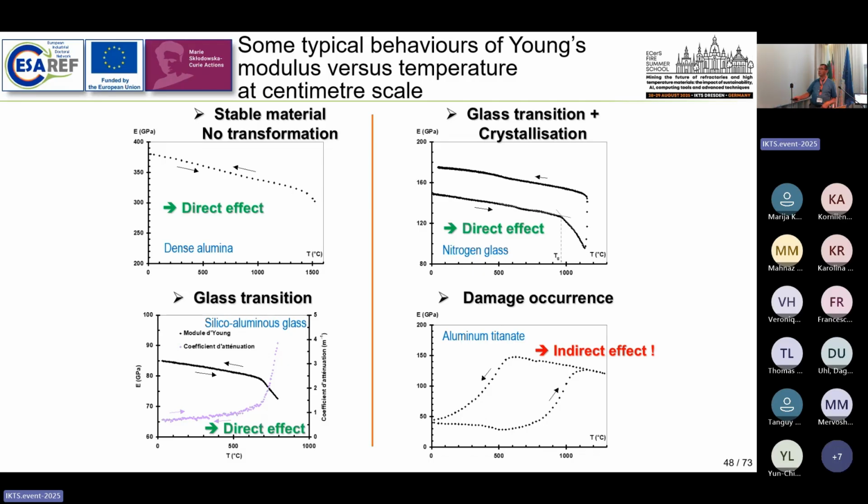Just crack evolution, you have a perfect signature of a hysteresis curve, which is a typical signature of a material containing cracks. Of course, for conventional mechanics, cracks are usually bad and decrease the property, but for refractory thermomechanics, cracks are a good point, and you should have cracks, and you should play with cracks.